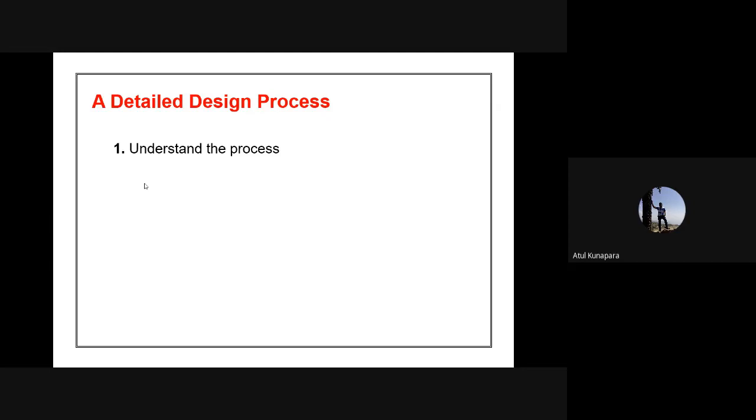You need to understand your process thoroughly in smaller steps, meaning what step by step process is going to be executed in sequential tasks. Your whole process you first need to divide into a smaller number of tasks, and those tasks are executed step by step. Then, according to your understanding of the process, you need to select the proper hardware and software required, that is, choose the particular PLC.